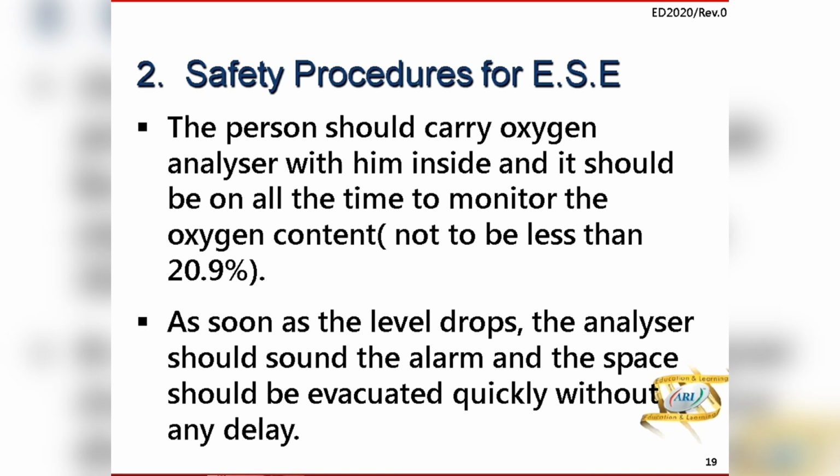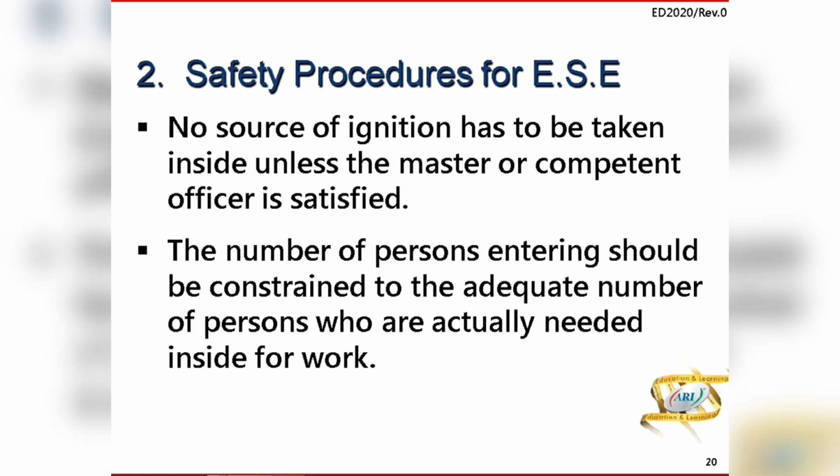As soon as the level of the oxygen drops, the analyzer should sound an alarm and the space should be evacuated quickly. No source of ignition has to be taken inside unless the master or competent officer is satisfied. The number of persons entering should be constrained to an adequate number who actually are needed inside for work. Extra persons should not enter there.